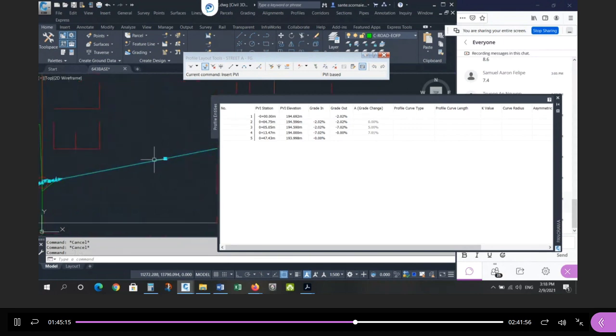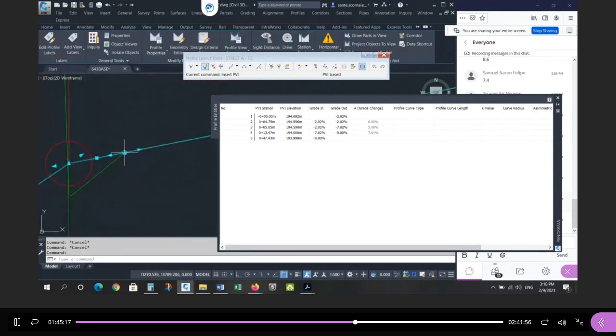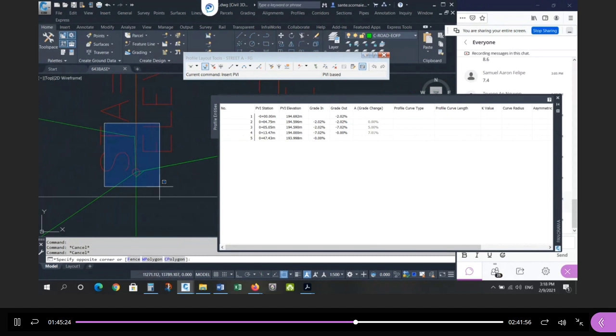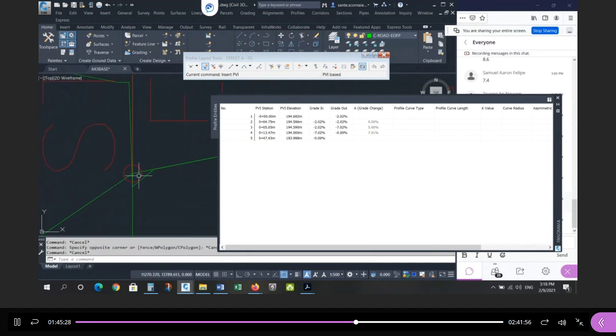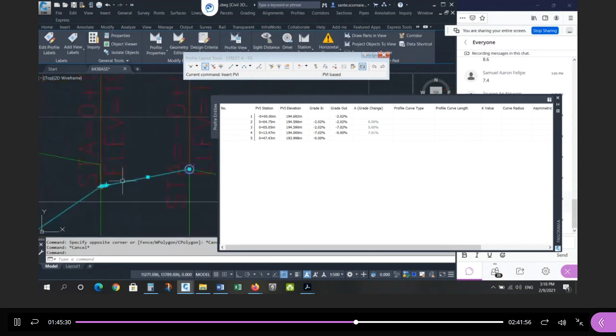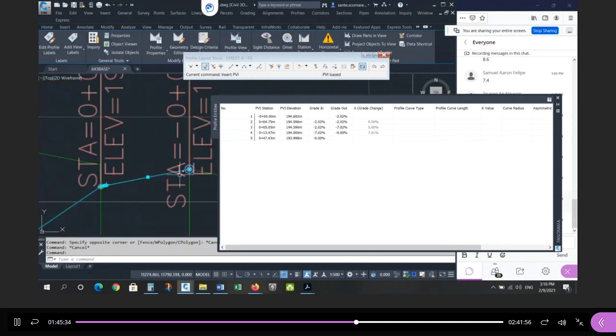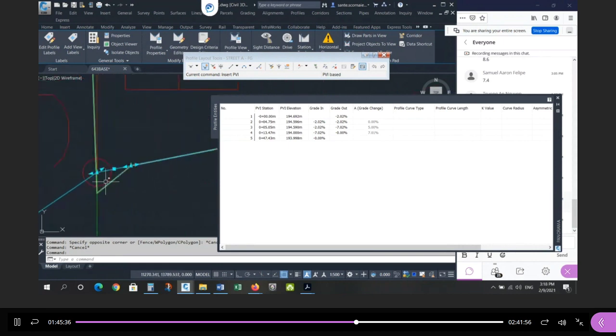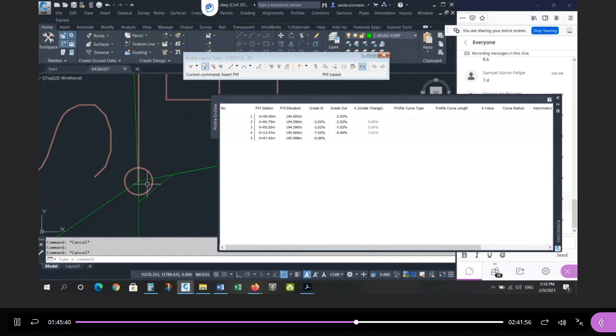And now I extended this pavement line from the edge of asphalt all the way across to where the gutter line is, the projection of the gutter line. We're going to get rid of this curb and gutter, right? It's going to be ripped out. So I want to extend all the way to the edge of pavement, the plane of the crown of the road, right? So if this piece here is 202, then the extension is also 202. So there's my first design point.